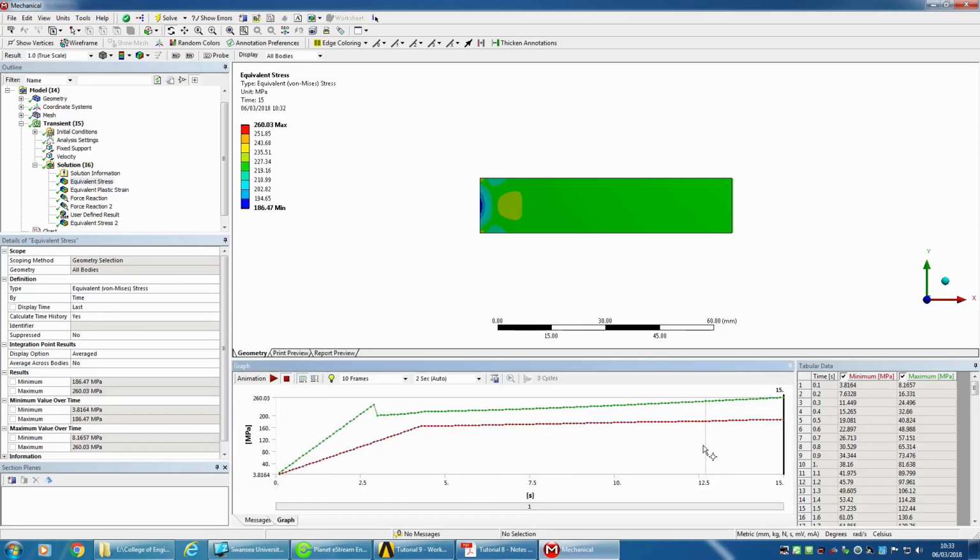So with that, if you click on the graph on evaluate equivalent von Mises stress and you have the graph enabled, what you can see there is a stress time curve. You can see that through the elastic period here, everything's fine. The stress is increasing roughly to the yield point, which we define in our linear elastoplastic. And then after that, it all goes haywire. It doesn't like the time step we've chosen, but we do manage to retain some of the stresses. And also what we're getting is a limit.